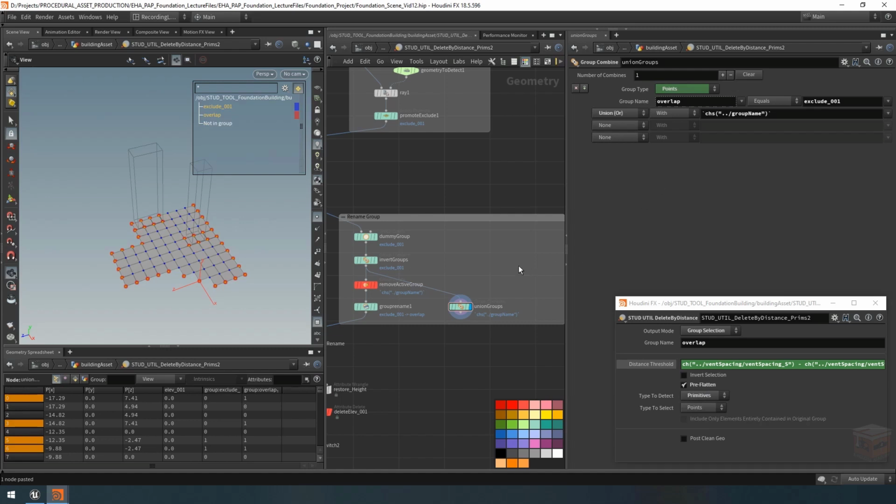And what the group combine node is doing in this case is it's actually creating a new group in the process, and it won't need our dummy group here because the first line on the group combine node is what first writes out the group, and then any option that comes afterwards basically gets added on after that group is already created. So at that point it won't error out.